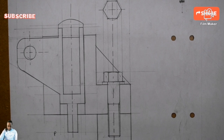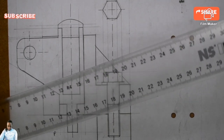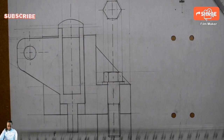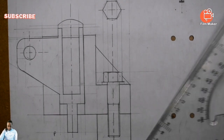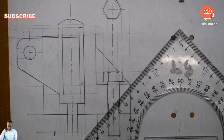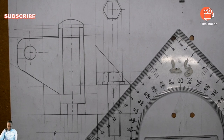So now we are going to draw section. So we are sectioning now. Because after you assemble, you have to section. Let me section now. So I'm going to start sectioning using my 45 degrees. All the hatches must be at an angle of 45 degrees and equally spaced to each other.